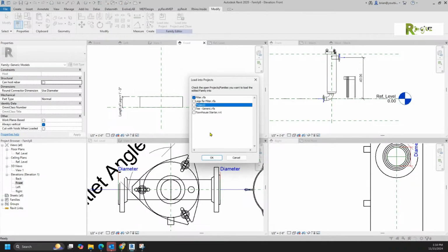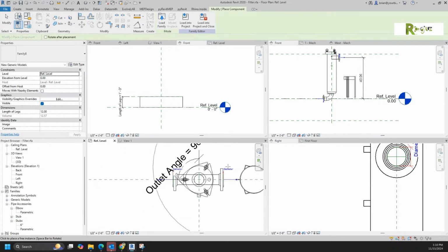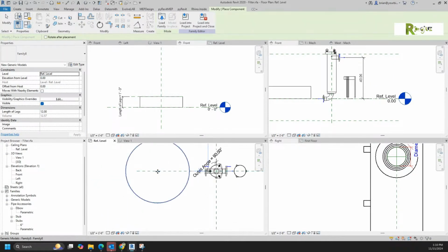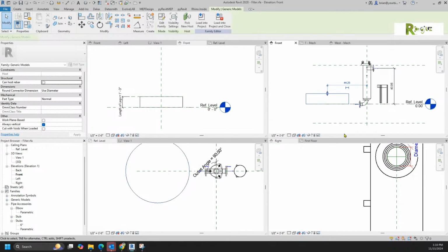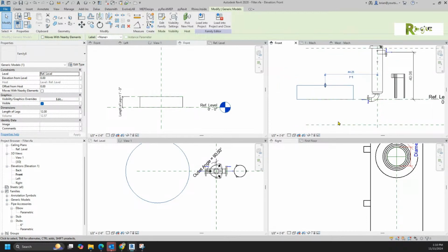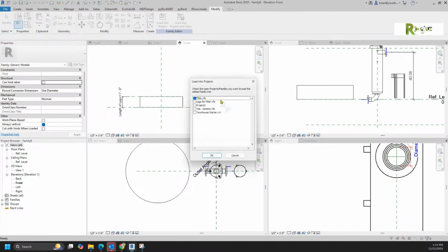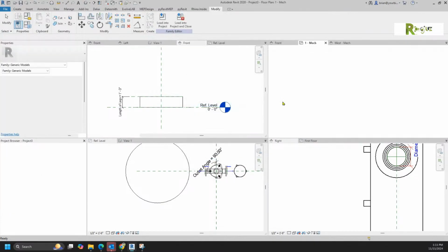You know what I didn't do, Brian? I took the extrusions of the angle pieces, the leg pieces, and I don't think I attached them to the reference level at the bottom, or that reference plane at the bottom. So in other words, the extruded piece is not attached at the bottom, so therefore it's not getting the grip. Yeah, just bear with me for a second, because that's not what I'm expecting to happen.